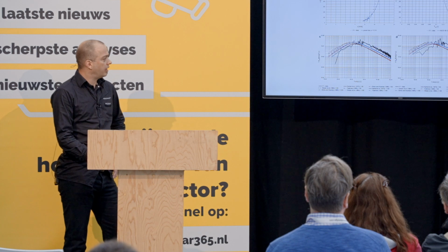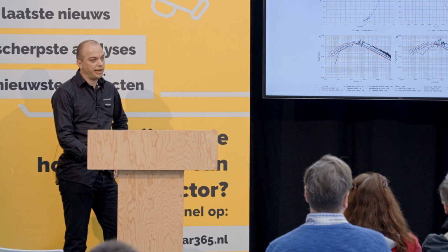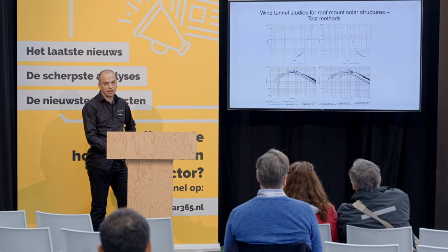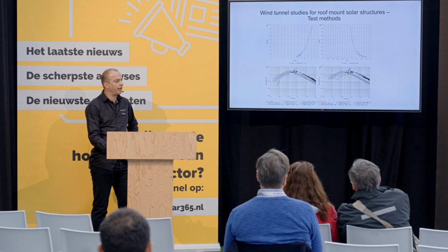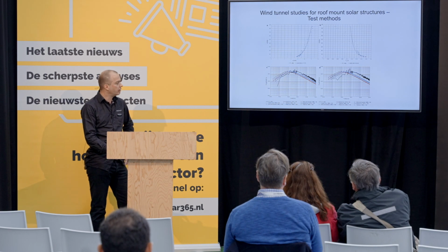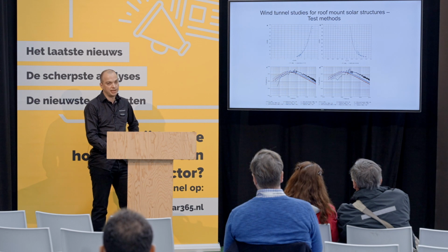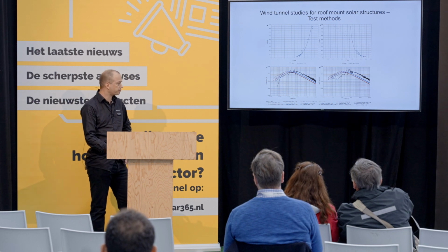This is how the flow characteristics look that we use in our wind tunnel testing. In the top left corner, there is the mean velocity profile matched by a power law. In the top right corner, there's the streamwise turbulence intensity matched by a logarithmic fit. And on the bottom, one can see the spectral content of the flow, the spectral energy content of the streamwise velocity fluctuations.